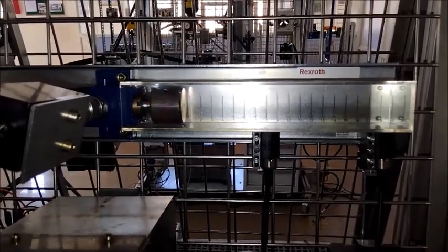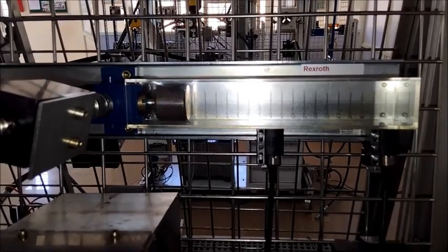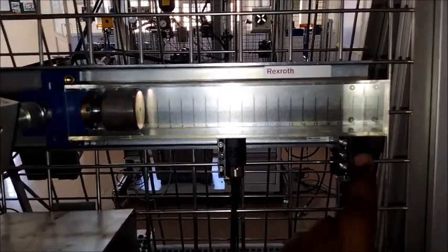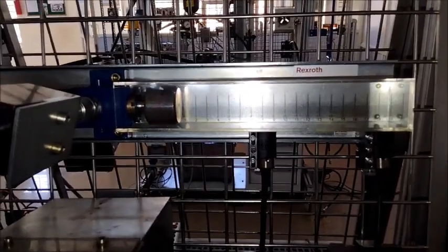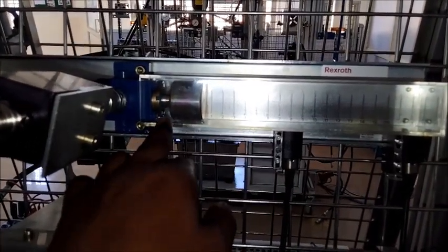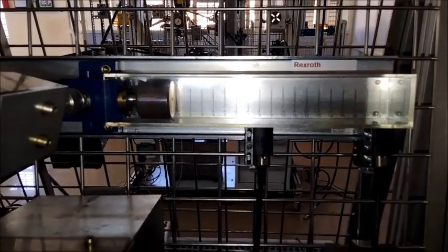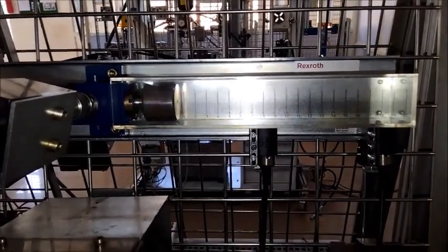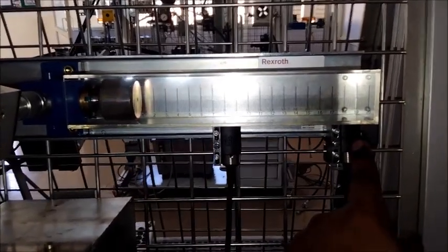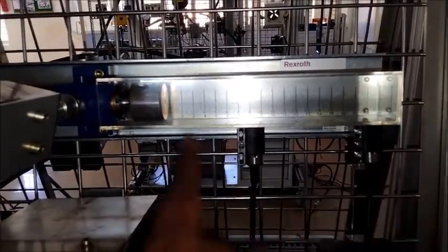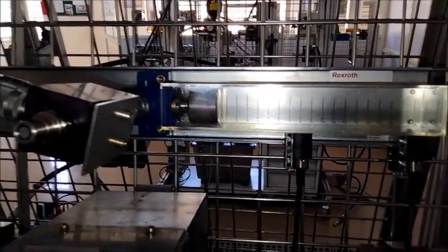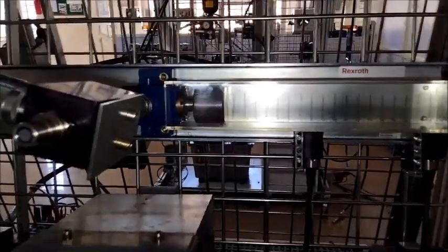So the speed of movement should be very, very less. That is what we call the feed rate. From B1 to B2 the speed should be very low. So there are two speeds in a single cylinder. Starting from the cylinder movement, it is high speed, but when it reaches B1, it should change from high speed to low speed. We are talking about feed speed. And when it reaches B2, the cylinder should automatically go back at a rapid speed, so that the total cycle time of the process will be less. Okay, so this is the requirement.